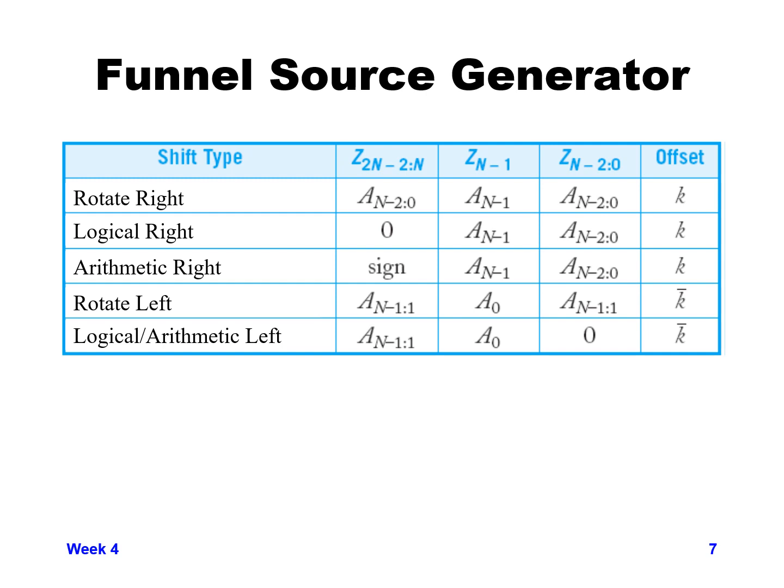You have to fill in your z values carefully, depending on whether you're doing a rotate right, arithmetic or logical shift right, or a rotate left, or a logical or arithmetic left shift. Depending on what type of shift or rotate you're doing, you have to fill those extra bits in with different values. So that's the main thing you need to know: filling in the extra bits is pretty complicated, and you have to know what to fill it with and have the right logic in place to do it depending on which function you're doing.